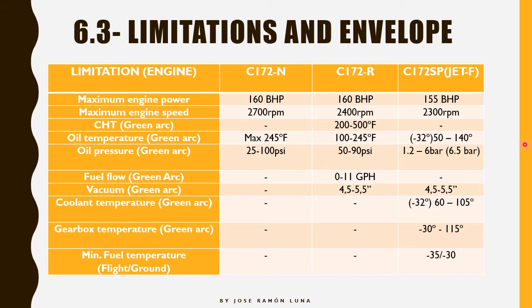The oil pressure, also a really important parameter. As we will see in the procedure section, the first thing we're going to be looking at after starting our engine is our oil pressure. We need that positive oil pressure right off the bat after we start our engine. As you can see, pretty much the pressure is going to be basically the same. 100 psi in the Cessna 172 November, 90 psi in the Cessna 172 Romeo.